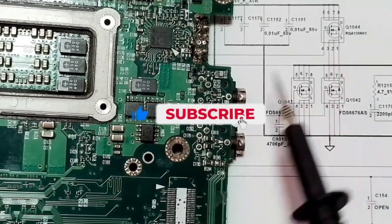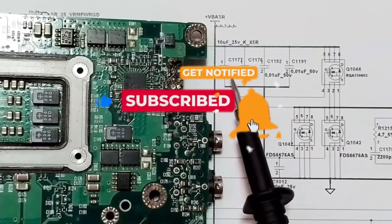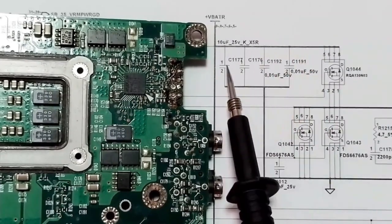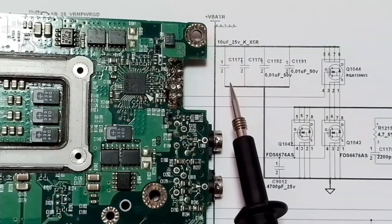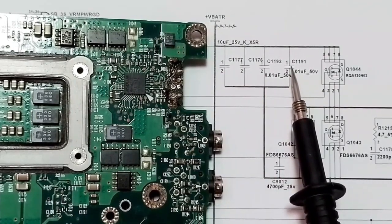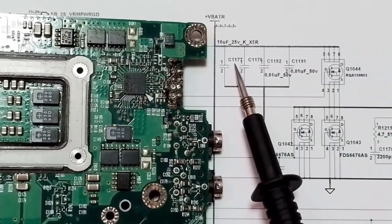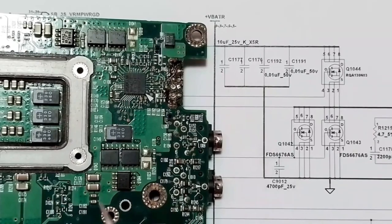So these two MOSFETs are these MOSFETs. And here, as you can see, we have 4 ceramic capacitors. This is basically the input of the circuit, where we have the plus VBAT. These 4 capacitors have the purpose of removing the noise from the circuit. Here we have C1177, the first ceramic capacitor.